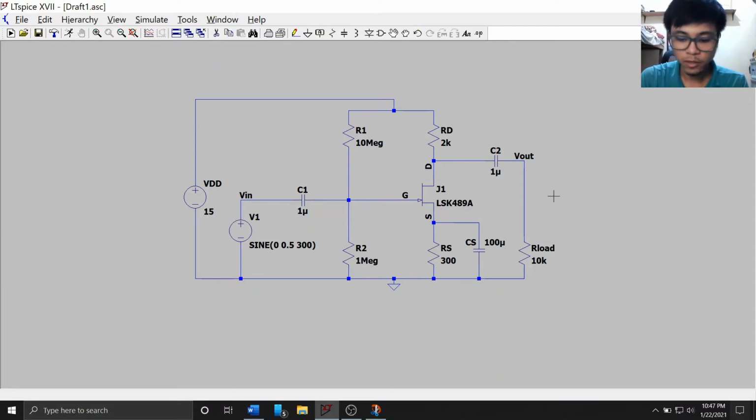So, field effect transistors are used in amplifiers, analog switches, integrated circuits, and oscillators. The advantages of JFET over BJT are that its impedance is higher than that of BJT. JFETs are also easier to fabricate and more temperature stable compared to BJT. However, FET amplifiers exhibit poor frequency response due to high capacitance and exhibit poor linearity.